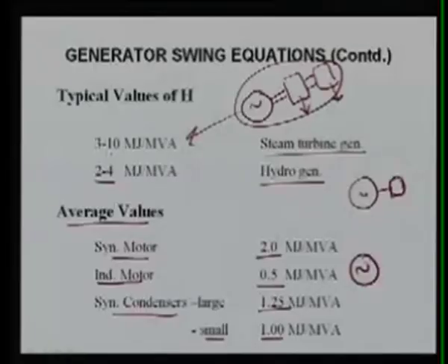To understand here, the synchronous condensers are nothing but some sort of alternators, but the mechanical power output, this electrical power output is 0. Means if you are using this generator and here PE is 0, you are rotating it to provide the reactive power only, Q, then it is known as a synchronous condenser.